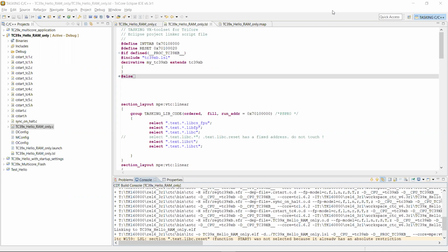That's a good question. Pretty smart question, actually. One advantage can be that there are spaces in RAM that may execute faster than flash. RAM access is faster than flash access. So what you can do, but that's a different subject, you can selectively allocate code, for instance, for interrupt service routines that you want to take a speed advantage from.